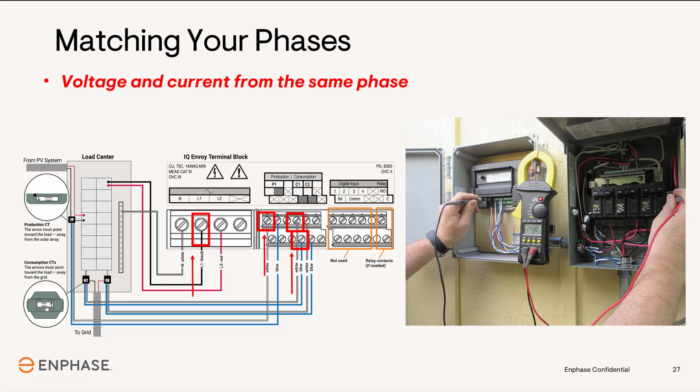Once the CT sensor, CT wires, and the gateway's power wires have been checked and corrected, check the readings in the Installer app again. There should be no more negative values. Okay, but what if you still see them?